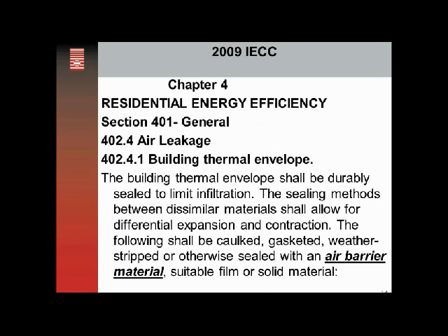solid material. And that key word there, air barrier material, is near and dear to my heart because here in Minnesota we've been dealing with air barrier language in our codes since about 2000. And it really was a breakthrough for us and our builders. Residential construction in Minnesota built after 2000 had this really specific code language that said we had to have a sealed and continuous air barrier. In Minnesota, there was a little caveat that it was on the warm in winter side of the envelope. It really changed how builders were putting things together.